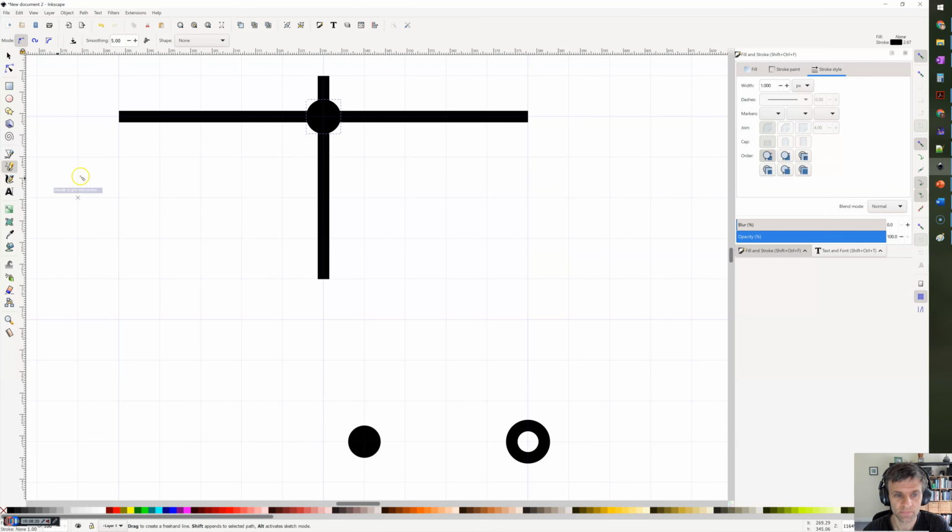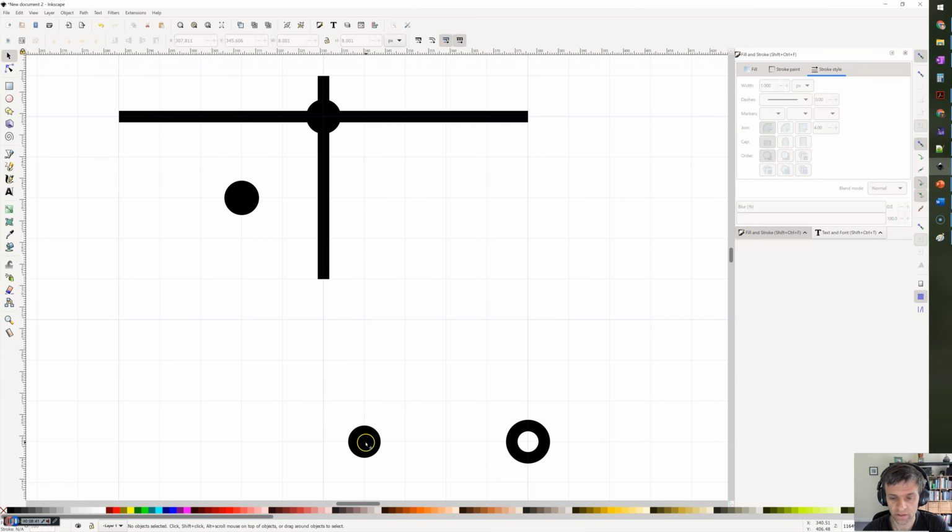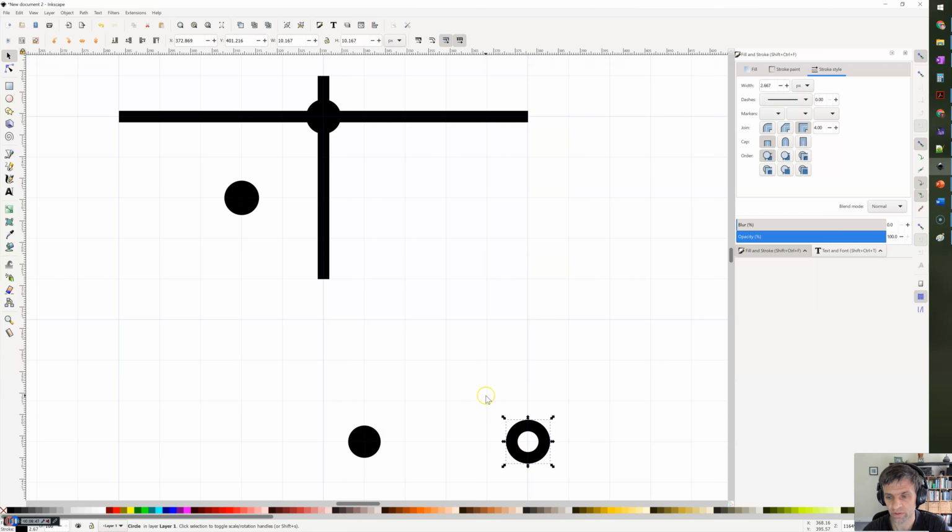With the pencil tool, I turn on the pencil tool and I hit Control Click, and boom, you get a nice dot there. You can define the size of that dot back in your preferences. So that's a quick way to just put dots all over the place at connection points in your schematic. I've also included in my template here a connection dot, as well as this shape, which is an open circle that's used to indicate a port in your schematic.